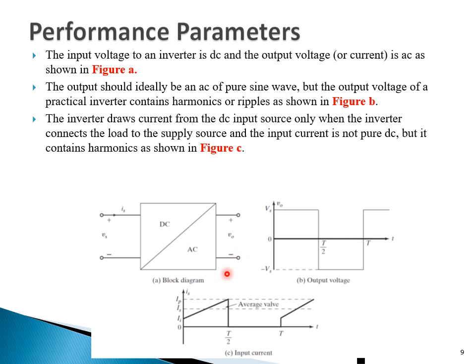And what we observe is the input current. The load current is supplied by the input current, but the waveform of the input current is distorted. You can see it rises initially during the on time, then it becomes off, and hence there are two levels of current here, right? Lower level and peak level, and the center of that we call the average value.